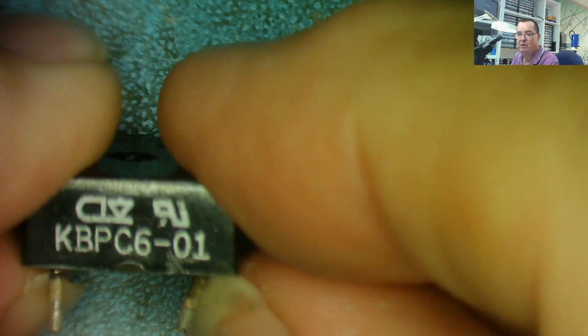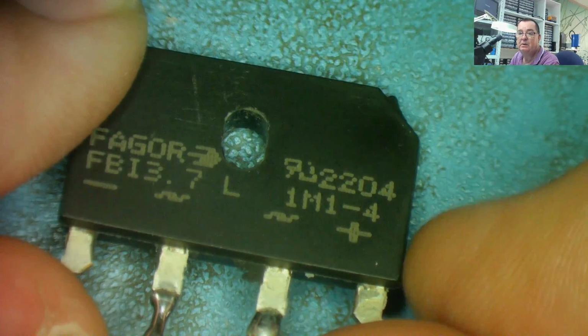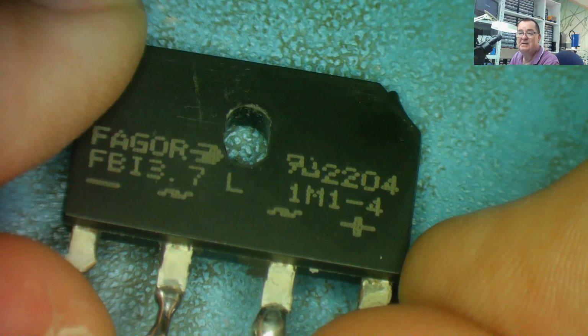The bridge rectifiers are always, I say always, I've ever seen, silicon diodes, so each one drops 0.6 of a volt, not Schottky diodes. We have a few varieties. You get round ones as well. 2 ACs in the middle, plus or minus.